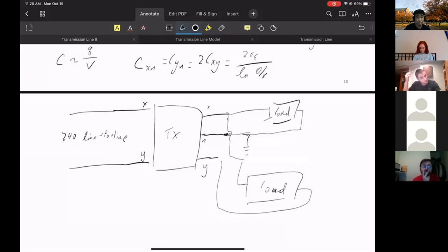So is that pretty much just saying that the neutral is like 120 volt almost? Yeah, so it's easier if you make that 0 and think of plus minus 120. Right, because you can balance out. You don't have to just connect from X to neutral to a 120 load. In your home, there are basically different circuits. Part of it, a breaker maybe on X to neutral, but another part is Y to neutral. So those are 120 apart. So it's a bit easier to think of neutral as 0, and other things are all 120 away from it.